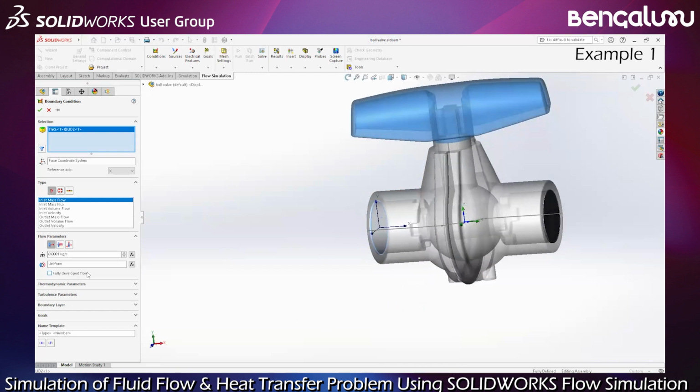And then I can say, okay, it could be a mass flow or a volume flow, and you remember I modified the default SI units to liter per second instead of cubic meter per second. So, I can say, for example, 10 liter per minute. It's small, but let's stay simple for the moment, okay?